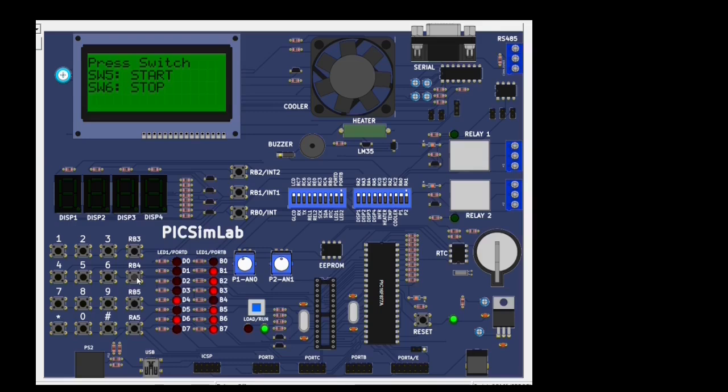Now, set time based on program plus level. Once program and water level are selected, time is automatically set using logic inside the set time function. The start screen shows the total time. The user presses switch 5 to start. Time begins. Washing phases are displayed: wash, rinse, spin, based on progress.